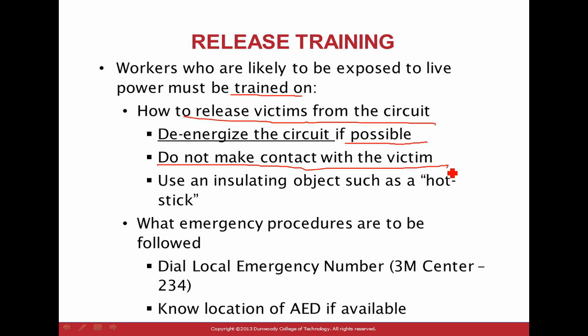Don't ground yourself. Make sure when you work with electricity, you learned this one a long time ago, you work with one hand. Don't put your other hand on anything grounded when you work on anything hot. You do not want to ground any part of your body where you're working on energized objects. So use an insulated object such as a hot stick.